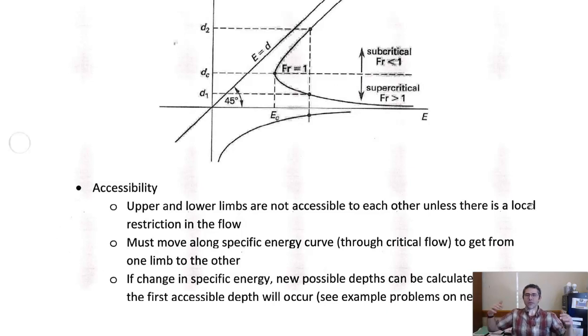If we want the water to be moving quickly from a high elevation to a low elevation, we want things to be really steep. But if we make things really steep, the flow is going to go supercritical, which is fine. But if we make our infrastructure really steep and then we reach a river or a creek down here and the flow is still supercritical when we hit there, there's going to be a lot of erosive force, a lot of velocity, a lot of chance of scouring that channel. We might not want that.